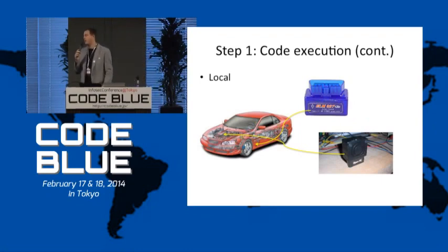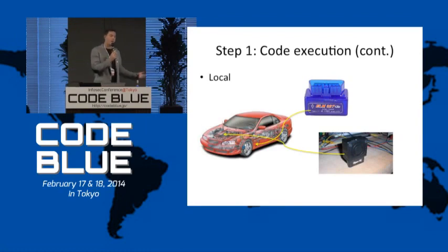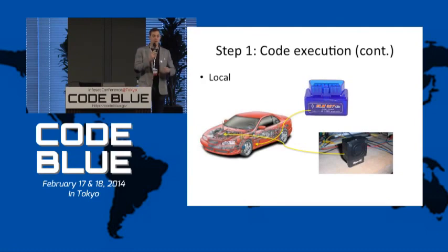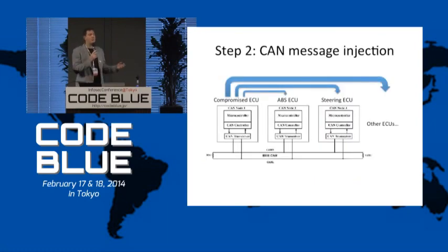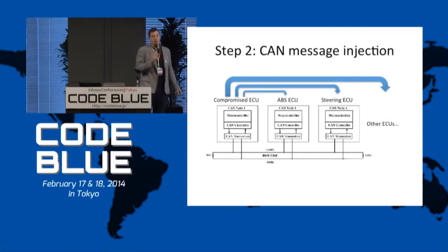The nice thing is some of them are open source, and I'm currently writing a custom firmware for my Fleet Karma device so it can read and write to the CAN bus. So that means all the attacks I'm about to show you that we did locally plugged in could be done somewhat remotely if you got this device plugged in and was around the car or had 3G capabilities. So that's how you generally go about getting remote access to a car.